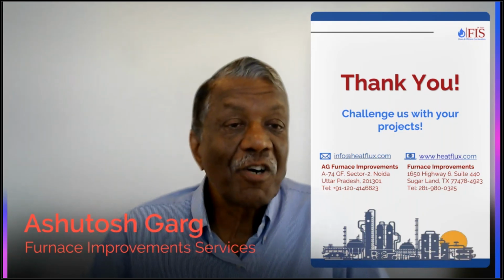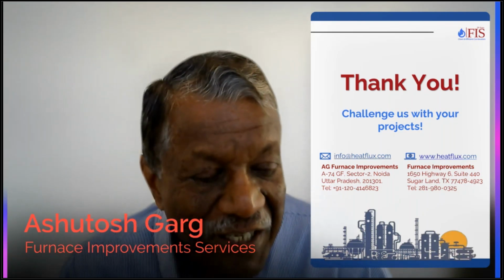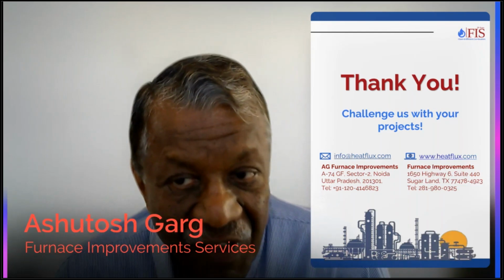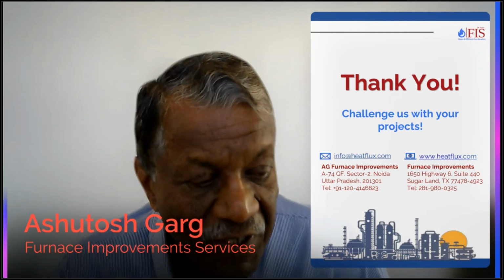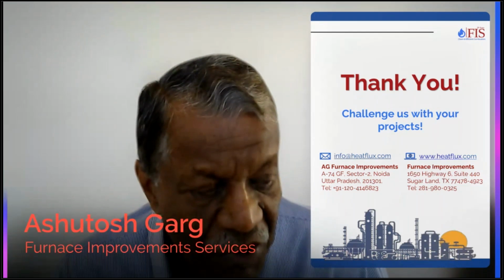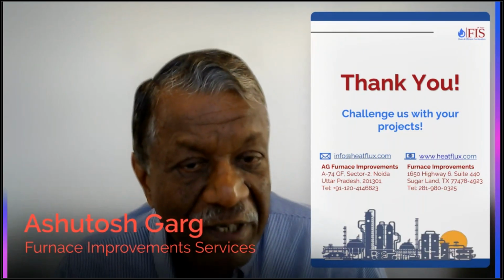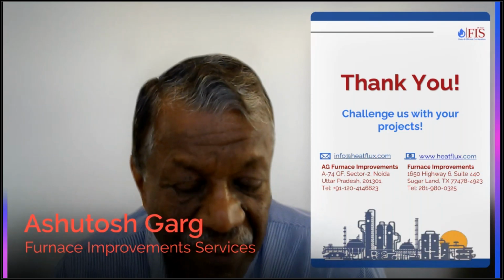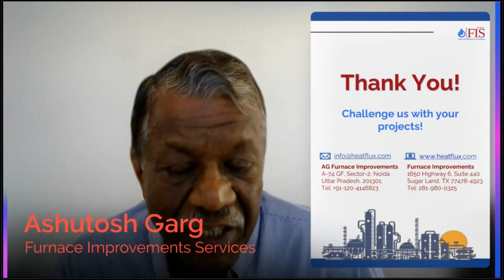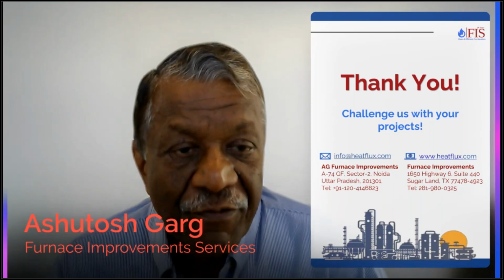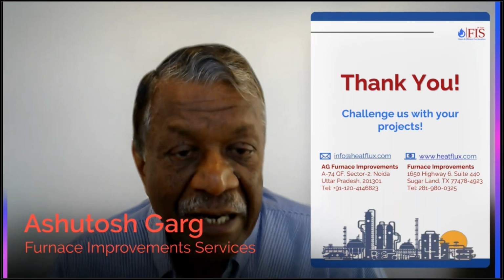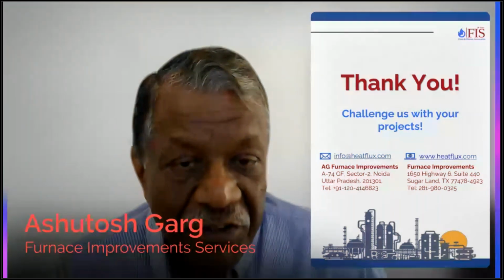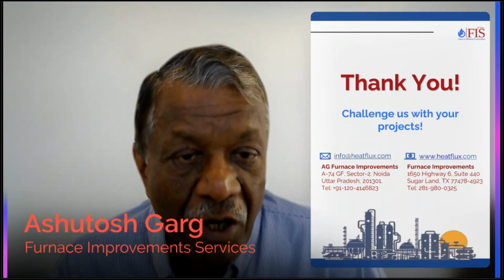Tell us about patents. Okay, so patents, we have three patents. We have inclined firing technology, which reduces the tube metal temperatures in crude heaters, vacuum heaters, any vertical cylindrical heater, by almost 100 to 200 degrees F. If you are experiencing high tube metal temperatures, please contact me. We will be able to help you out.